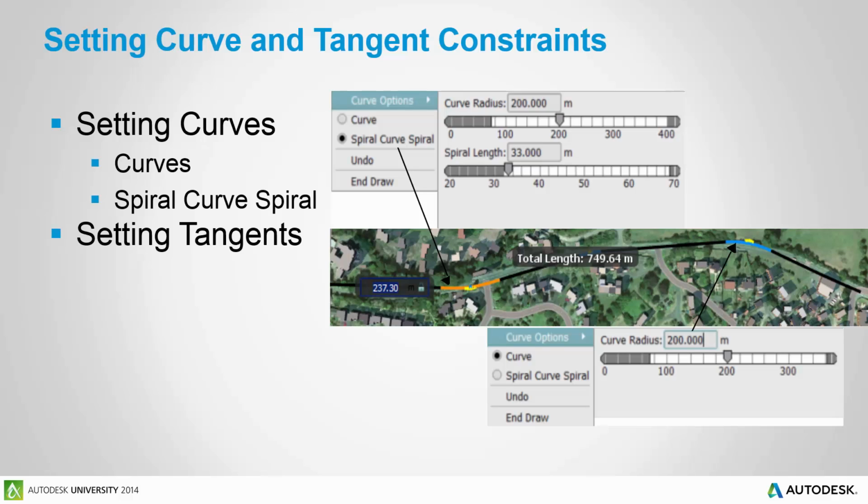The design speed property of a road determines the default criteria that's available as you start creating your roads with spiral lengths and your maximum or minimum curve radius. As you create the design road, you have the option to adjust the type of curve being used and its radius within a set of parameters that are determined by the design speed. So for instance, you can see here, this gray area means that I cannot set my curve any smaller radius than the number that's just before that gray area. And I can't go beyond the maximum either.